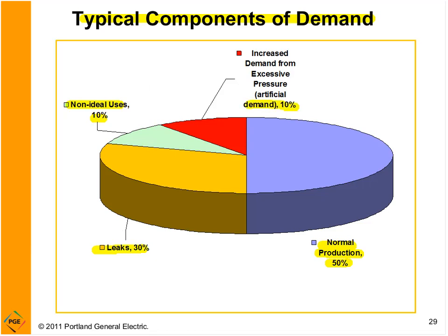and this artificial demand thing. Air pressure's jacked up. This happens all the time. Piping systems are inadequate. There's lots of leaks rushing through the pipe to create pressure drops. They jack up the pressure. Artificial demand is increased in areas that see that high pressure, and it's really just a whole bag of no good.